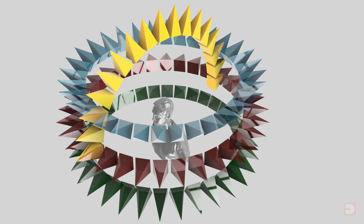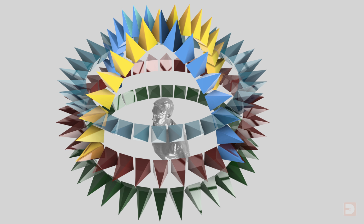When capturing images for photogrammetry, the standard plan is to take photos at 10-degree intervals in a loop around the object, with the camera always facing in towards the middle. Then repeat that loop at least 2 more times, one higher and one lower, separated by 30 degrees from the initial loop. Then take 2 or more sets of photos, again at 10-degree separation from one another, this time in an arch from one side over the top and down the other, repeated 1 or more times, starting from different sides of your object.